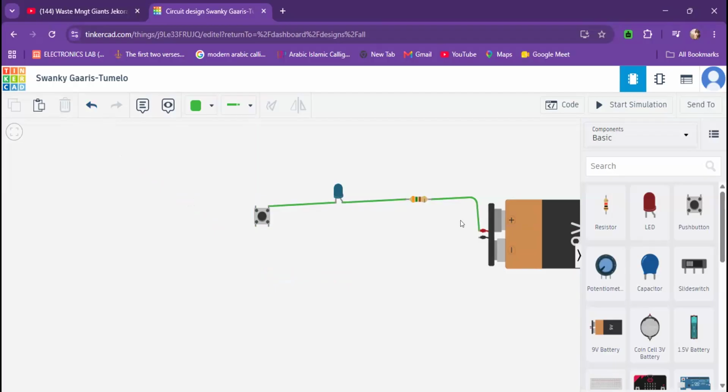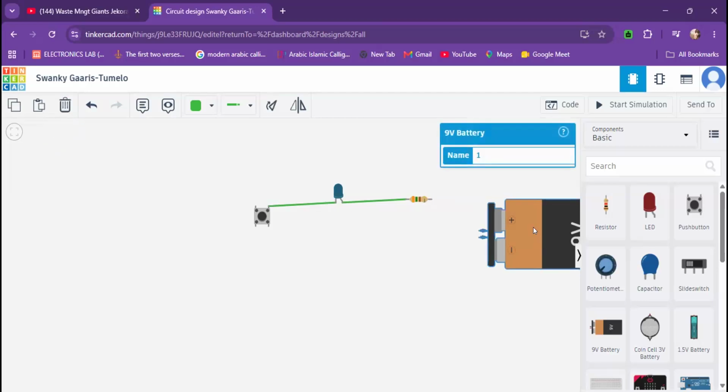Undo, there is gone. Now, let me take off the connector from the battery. Selected, then you delete. Now you select the battery. You see it has been selected. Yes. As it's selected, you press on mirror. This mirror will turn the direction, or you can press on M to turn the direction for you. Hence, the positive has come down and the negative is gone up.